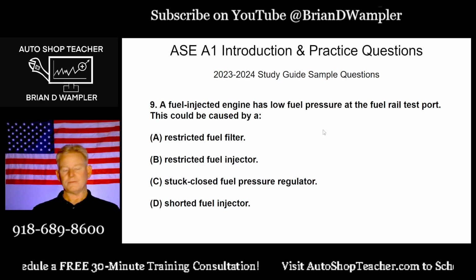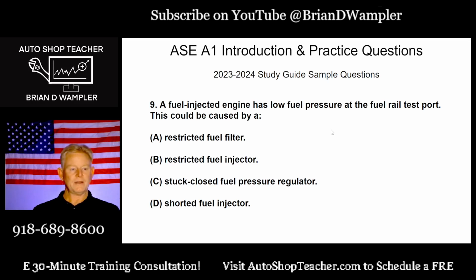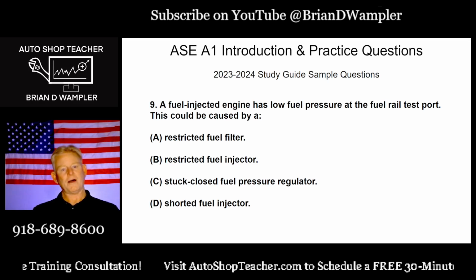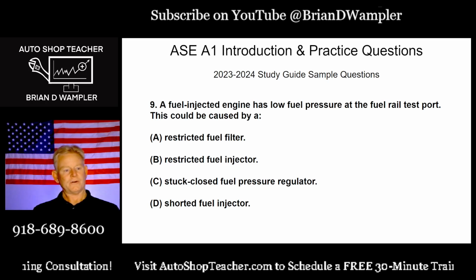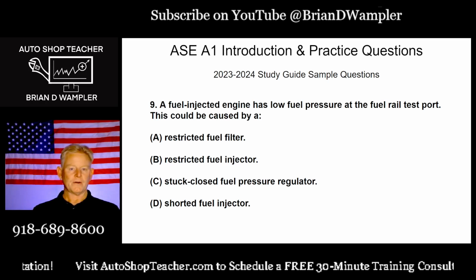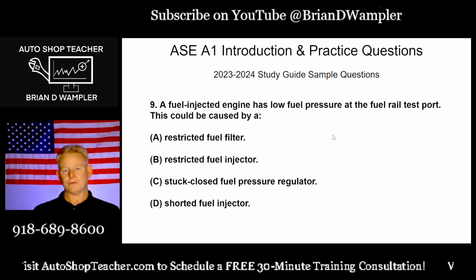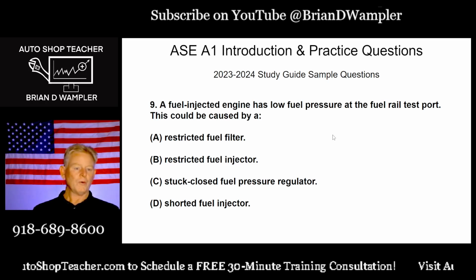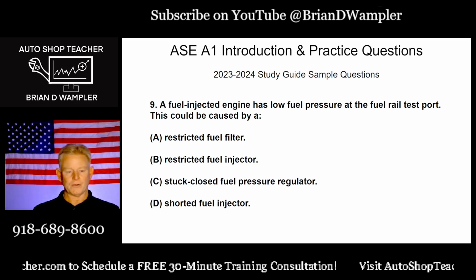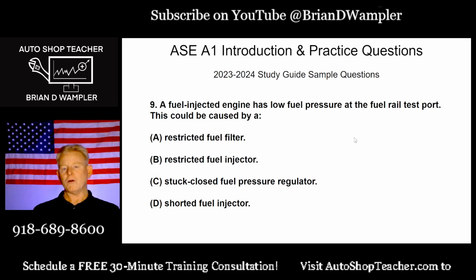And just ask yourself, as you go through each of these, could a restricted fuel filter cause that? Could a restricted fuel injector cause that? We're talking about the supply, the fuel pressure. If the injector is restricted, would we maybe be talking about cylinder misfire or a cylinder that's lean? A stuck closed fuel pressure regulator. Well, only if you're familiar with how a traditional mechanical type fuel regulator works, would you know what stuck closed would mean?